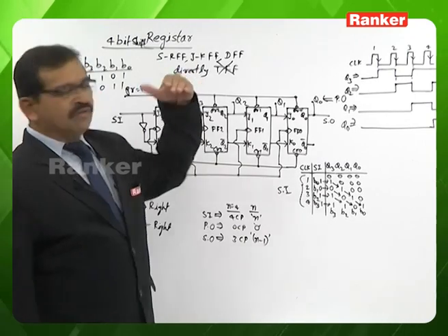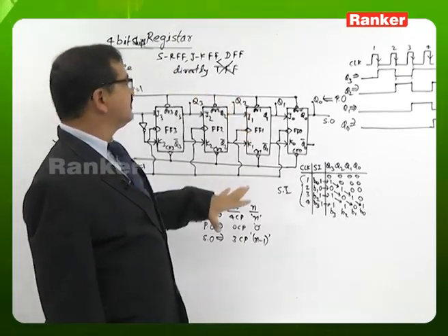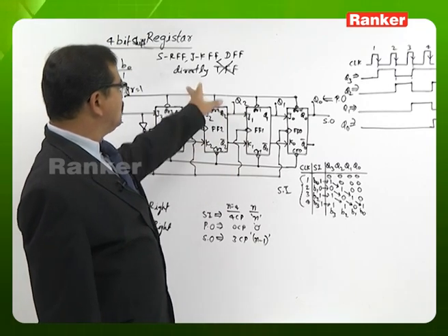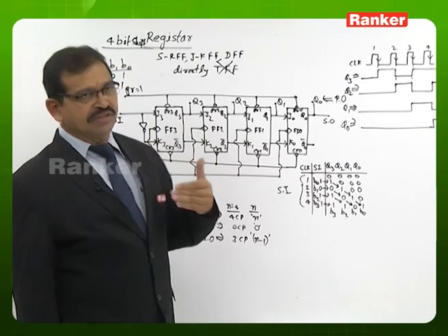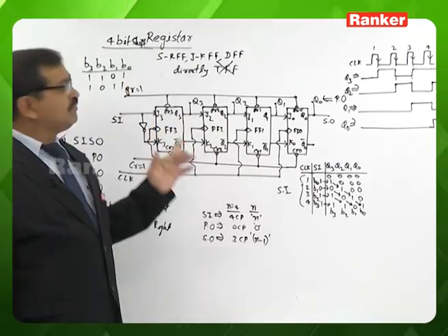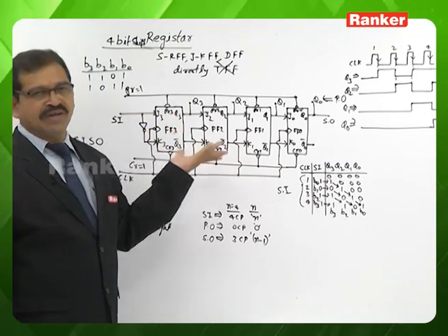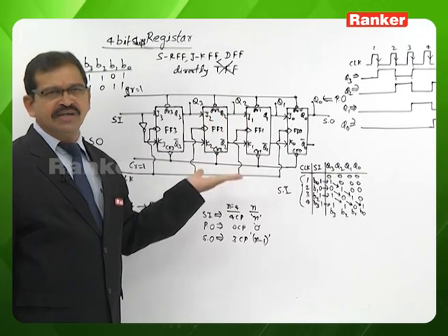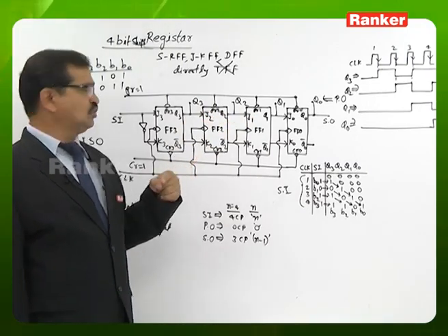In the beginning of this topic, we were talking about realizing registers, and we are unable to use T flip-flops directly. Why is it so? Let us try to discuss now. In this register circuit, we are using JK flip-flops. Based on the connections, we are able to recognize that at any moment the J and K inputs are not having a chance to be 1-1 inputs.